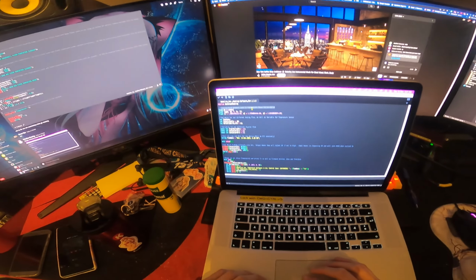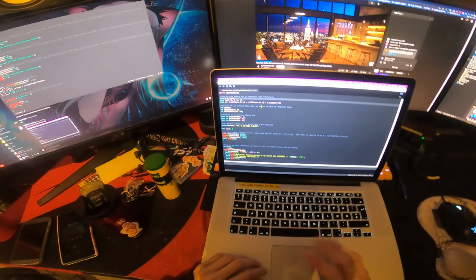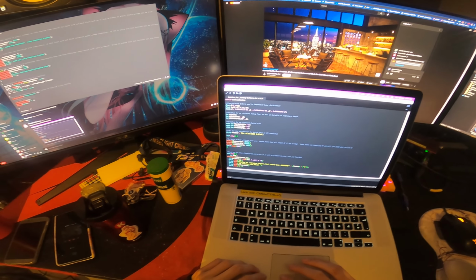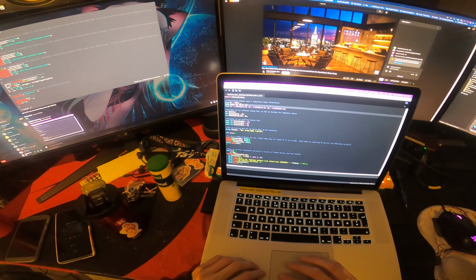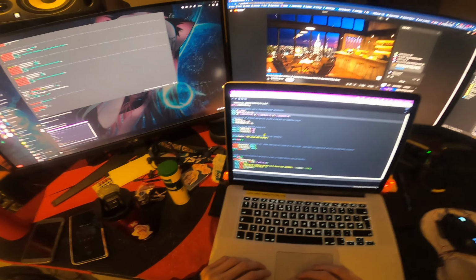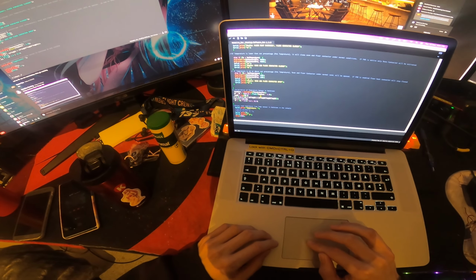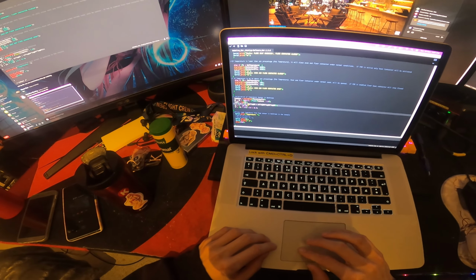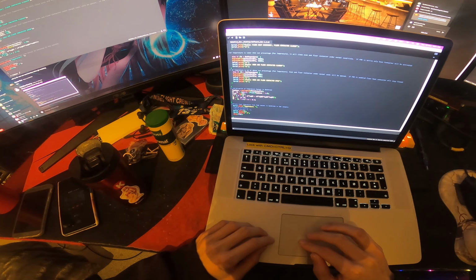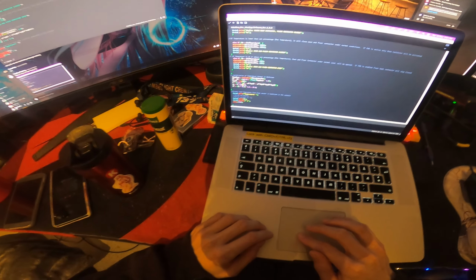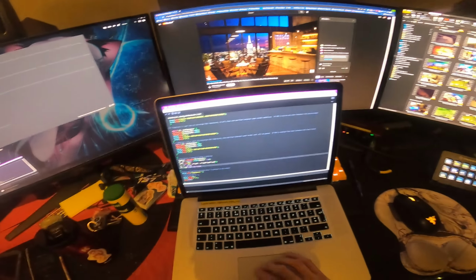So we got our floating point numbers, which are used in the temperature sensor calibration: R1, log R2, R2, T, TC, and TF, which are all floating numbers. Those are used down here, the logs being multiplied, and then the temperature variable equals, and stuff is done down here.